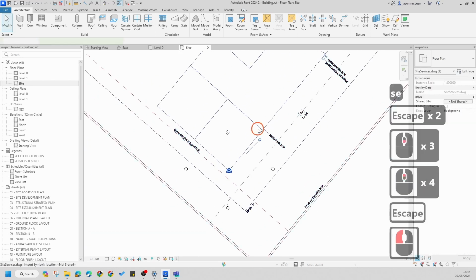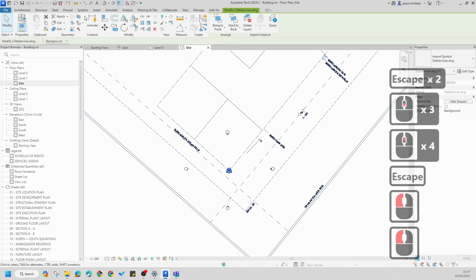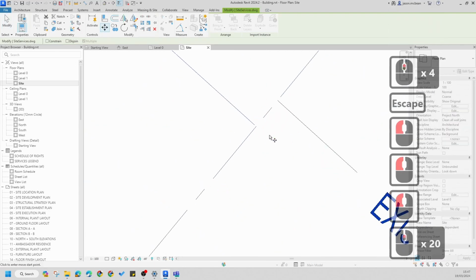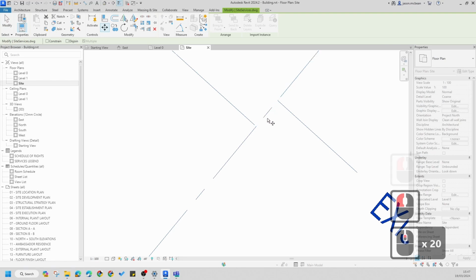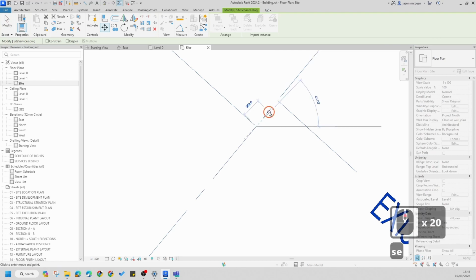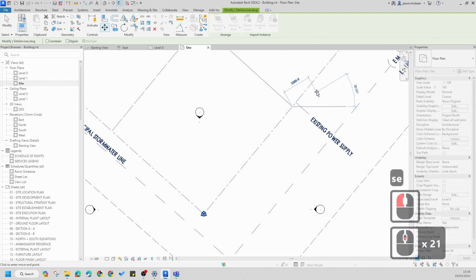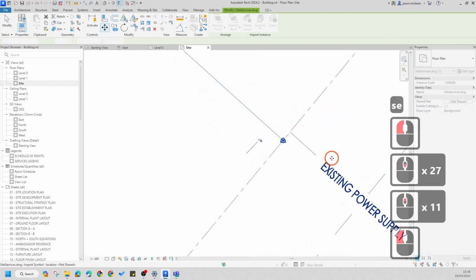Now, I'm going to unpin this drawing file and move it. I'm going to be quite accurate. So hover on this bit of line work and I type SE, snap end, which means it snaps on the endpoint, and I'm going to put this right at our origin.